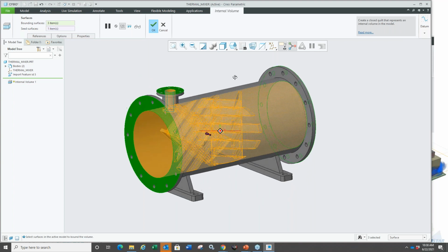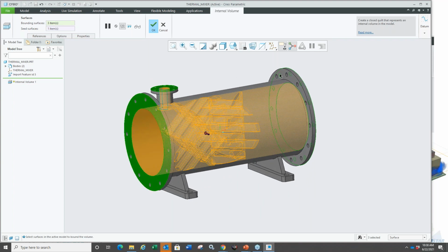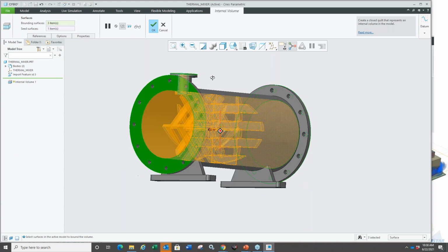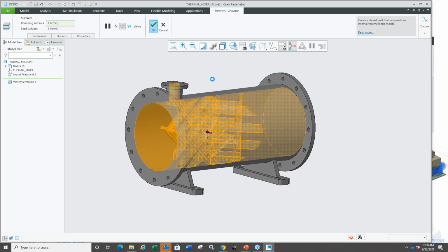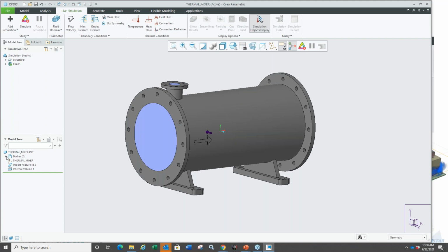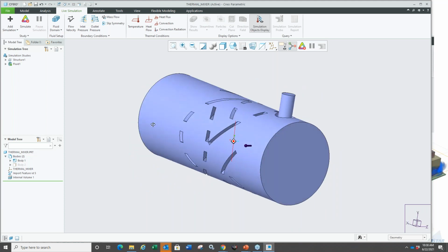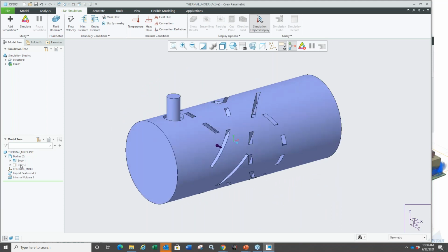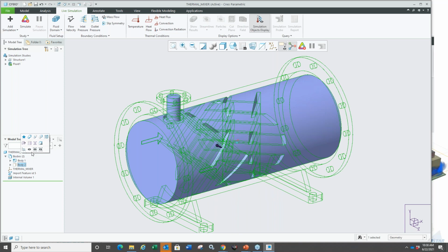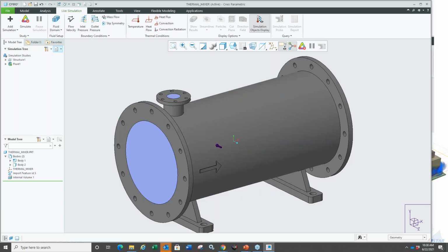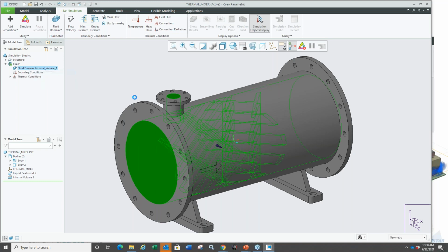The software has that built in, wherein as I select these 3 outside surfaces, it knows to give me that domain. In Creo 7, we have the multi-body concept. If I hide the outside design, you see the blue fluid domain for which I will be assigning a material here, right? So let's say I want to go to the fluid domain, and I can just go assign material.